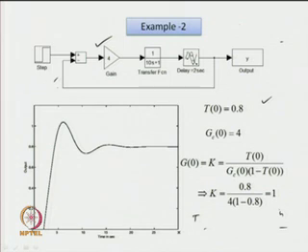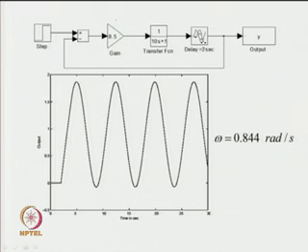proportional controller gain. So, the proportional controller gain of 4 will be increased. We will try with various values. By hit and trial, when the proportional gain is 8.5, then we obtain a sustained oscillatory output for the closed loop system.